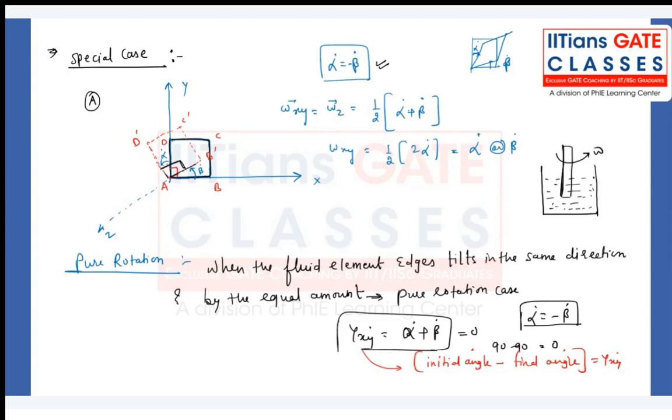So when we rotate this fluid, even though it has viscosity, even though this is a viscous flow region, this fluid element in the container will not take a different shape, right? Whatever the initial shape is, that will be the shape after some time also. So this is called forced vortex flow. This forced vortex flow is a pure rotation example.